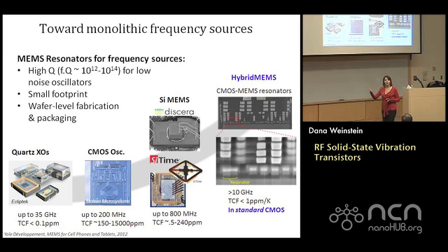You apply a voltage across an air gap capacitor, there's a Coulomb force, it pulls the thing together, right? And you can move these structures that way. They still require their separate processing because these are released structures. Right? And they're limited to low frequency based on lithography, based on the fact that you have electrical connections from one chip to another, where parasitics will kill you if you try to do this at higher frequency.